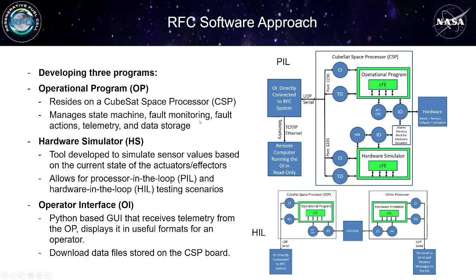It's a workhorse. Second, the hardware simulator. This is a development tool used to help simulate sensor values based on the current state of the actuators. This is used to test to make sure that the operational program is running properly. The hardware simulator allows us to test the operational program in multiple scenarios, whether processor in the loop or hardware in the loop.